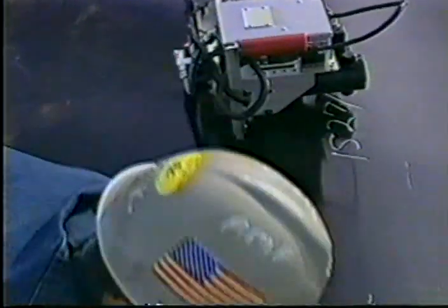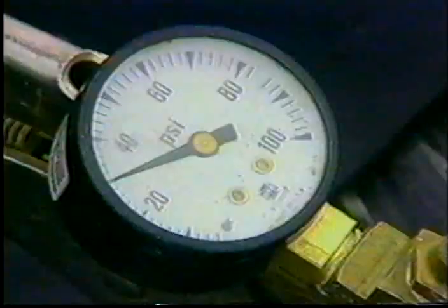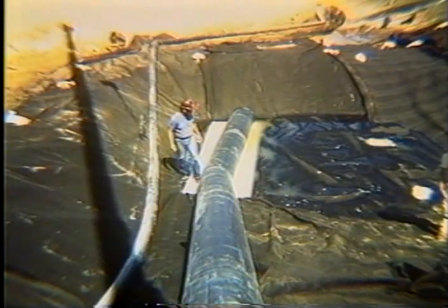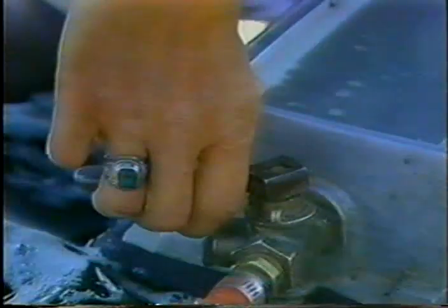The seam integrity of geomembrane liners is obviously vital. Many ingenious devices are used for seaming and testing. This is dual wedge welding, which leaves a space between two separate weld tracks. The whole seam can then be tested for leakage by air pressure. In areas that can't be accessed by a machine which makes a double seam, a hand welder can be used to make a single one. In this case, seams can be tested with a vacuum box. As suction is applied, leaks show up as bubbles.